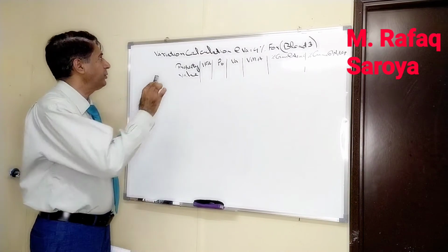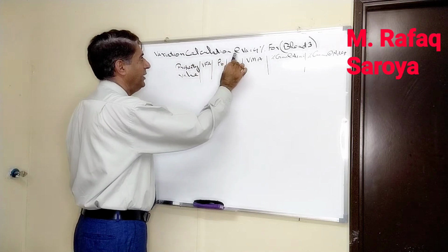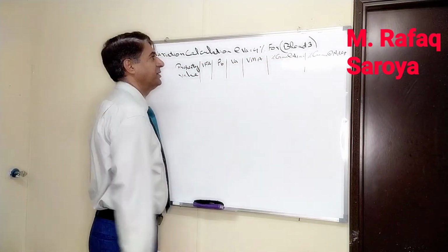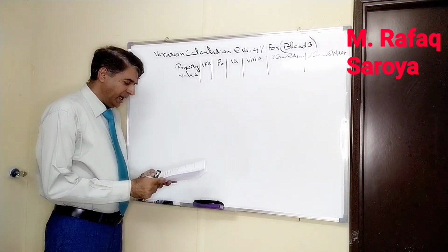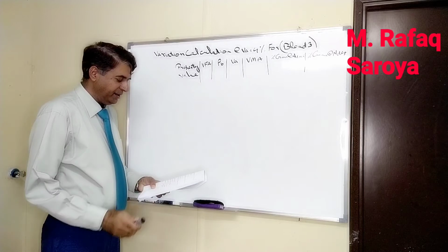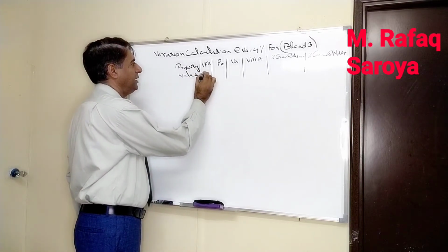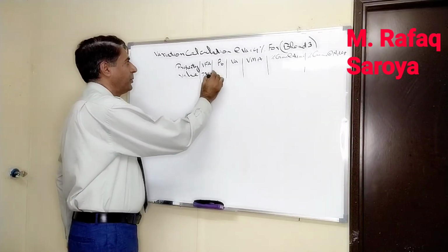Now we are going to make the variation calculation at the rate of VA equal to 4% for blend number 3. Whatever values we have already calculated for this blend are given over here: 73%. The percentage of bitumen is 4.6%.